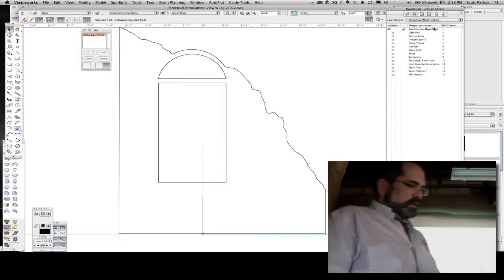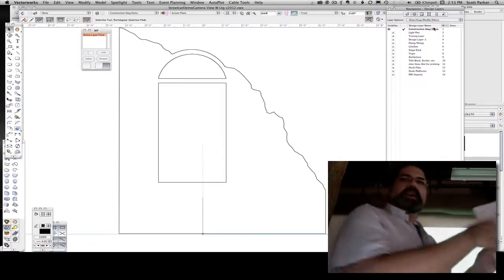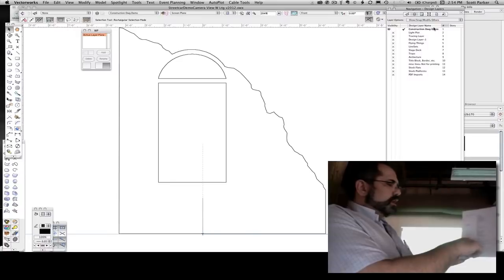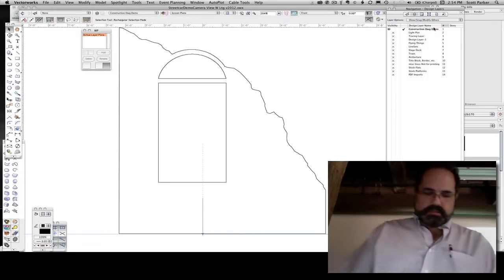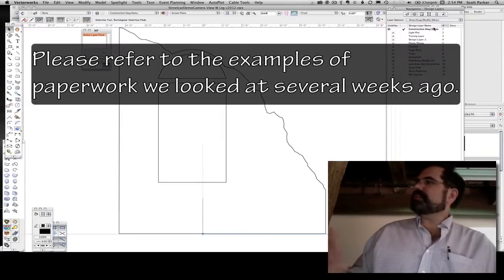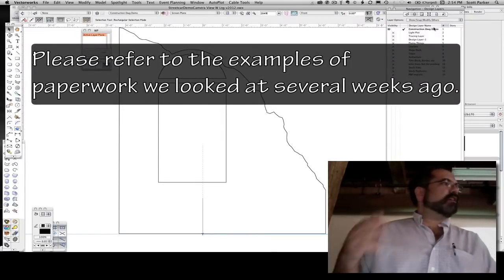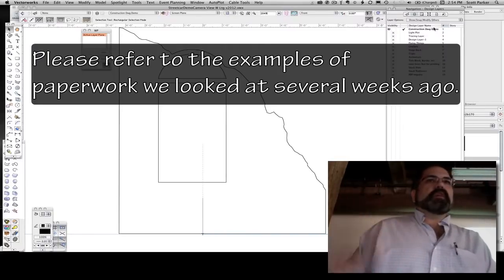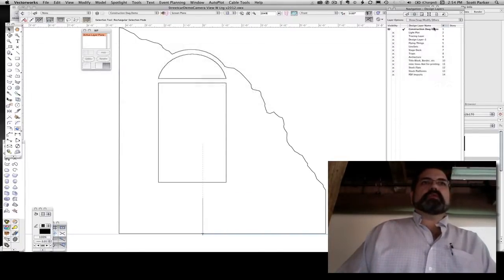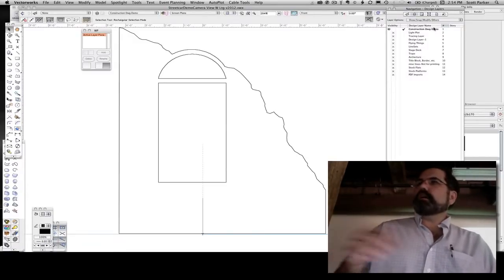There is a note down here, down at the bottom. I don't know which side I gave you. I didn't number the sides, but it says all drawings. So all drawings likely want to have a border, a title block used properly, and what I mean by that is including the correct information, like your name, the show name or the project name, the scale, the date, all that information that we would include in a title block. Line weights and line types. Center line should always be long dash, short dash. Line types for other things.